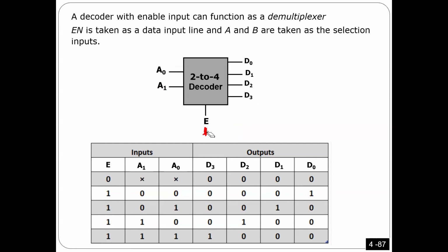But if the input is 0, for example, if I work with D2, this one becomes 0, okay? So that's why, if for example I want to use D3, just as an example, here I'm going to put number 2. Number 2 is actually 1, 0. Now, based on what the input is, this one should receive 0 or 1. If the input here is 1, okay, the decoder is enabled, and because it's enabled, and because I selected D3, it is going to receive 1 here, similar to the input here.